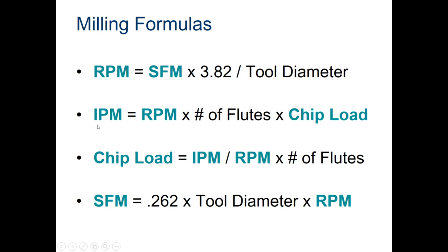Same thing for this. This is our feed rate formula, and it's, again, not any different than what we looked at. It just looks different because we're using different terminology. But inches per minute, that's our feed rate. And it's our spindle speed, or RPM, which, if you remember in our formula, we had that RPM value as our spindle speed times the number of flutes. So again, that was in the formula we saw for speeds and feeds. And then chip load is a different term than what we used, but we had that value we looked up, the tooth feed, that we pulled off of a chart. That's what chip load is.